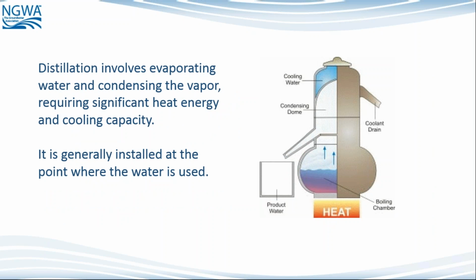We have distillation as a treatment scheme for removal of fluorides. Distillation is actually the evaporation of pure water, leaving virtually everything back in the vessel. So when that vapor condenses back on the other side into pure product water, unless you get a little carryover, you're talking about pure H2O in that vessel. We don't really see that in the drinking water industry as much as industry and laboratory quality type water, but certainly distillation is a methodology for removing fluoride and producing a very, very clean, pure water.